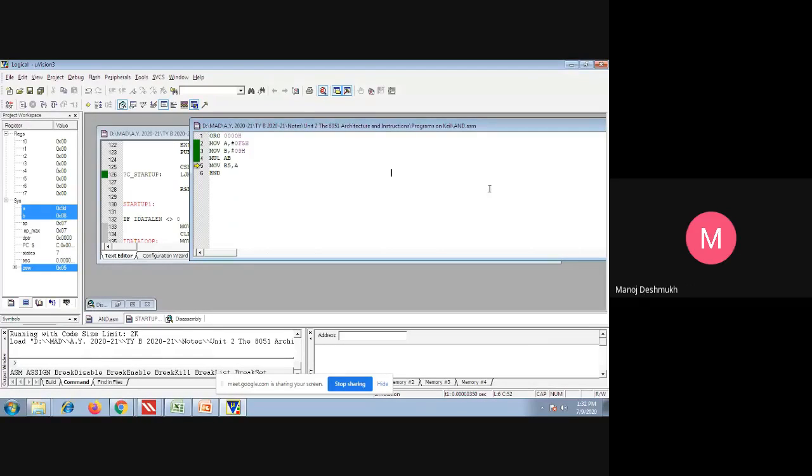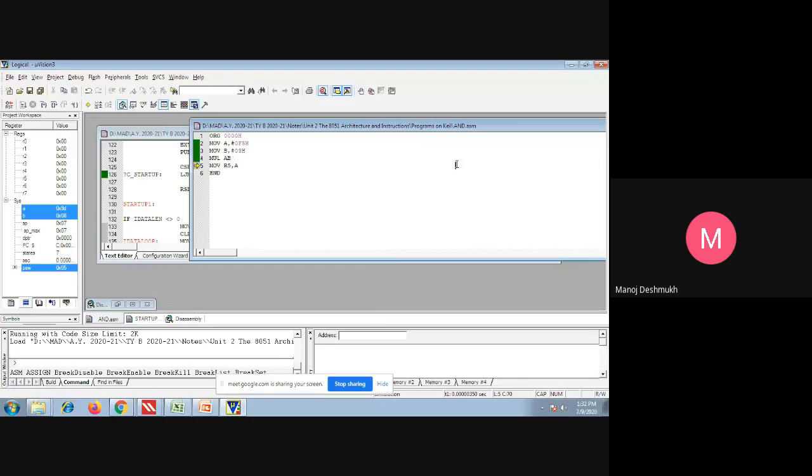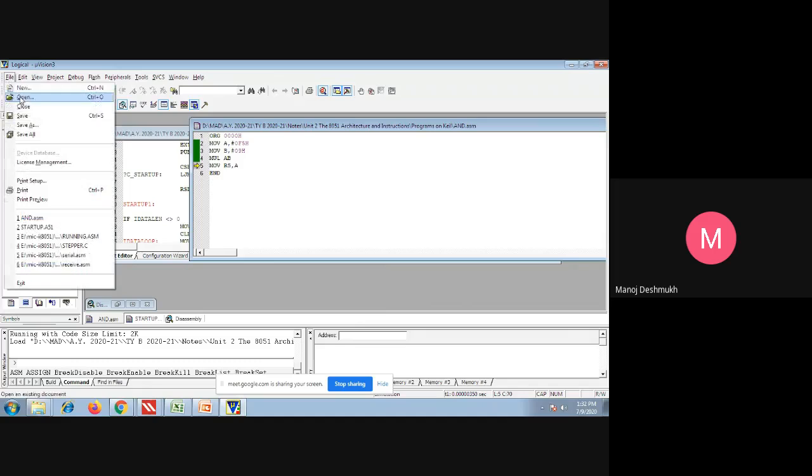Okay. So when we start the Keil microvision, in that file edit, some menus are there. After that, you go for project, new project, and select your controller. After selection of controller, this blank window is there, gray color. After that, you have to select new file. And this is related to your text file.